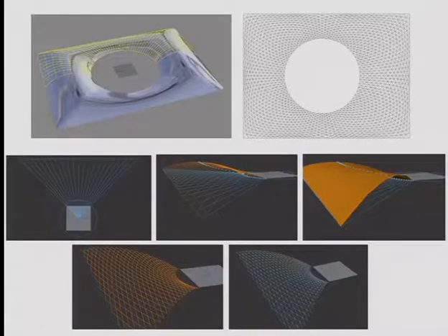So this is the final geometry, but I can tell you there were so many studies about how to make these triangles. What is the geometry of these triangles? Well, it is defined first radially, so you divide the boundary in a set of points, and then you make sure that they all converge to the center. And then from that you define some specific arches, which are not catenaries. In this case, they used a specific function to define an analytical surface, because it was done before 2000. Generally, they preferred to do that before 2000.